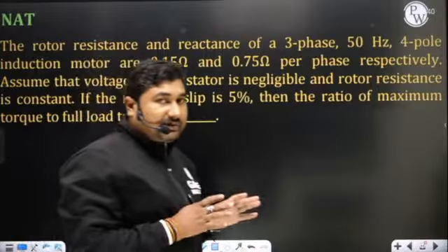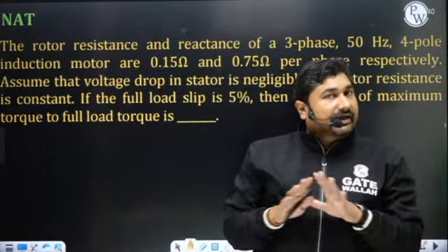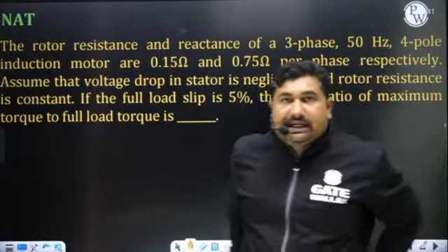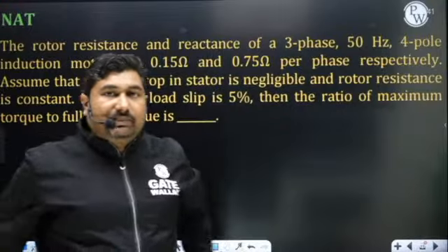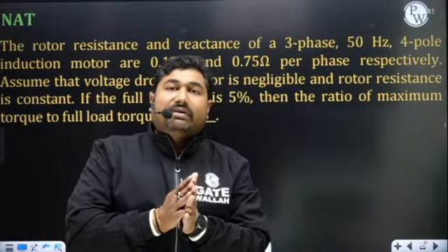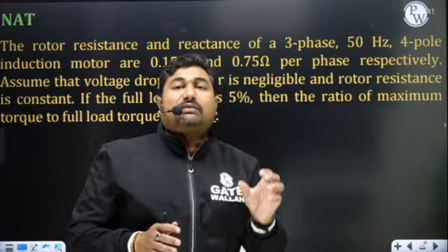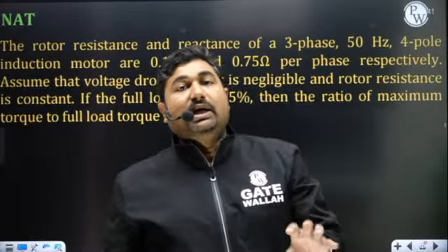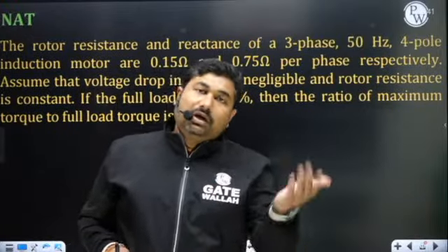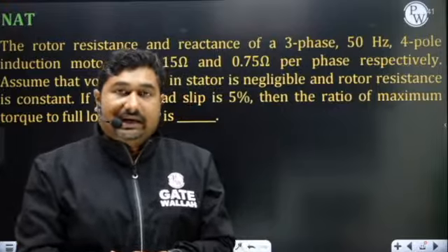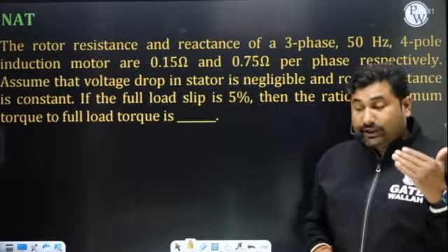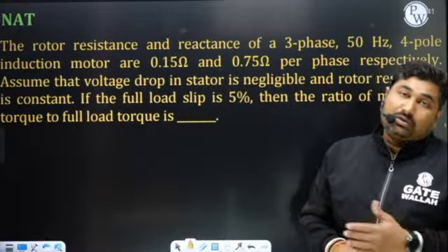Hoping this one question is going to help you solve any question based on the auto transformer. Always remember that in the first connection, which is additive polarity, both the two winding transformer voltages are added, and that will become the HV side, and the high voltage side of the two winding transformer becomes the LV side of the auto transformer. If you treat this to be VH by VL of the auto transformer, you can use the formula of A auto. You will always get the highest kVA rating when you connect the windings of the two winding transformer as the auto transformer.